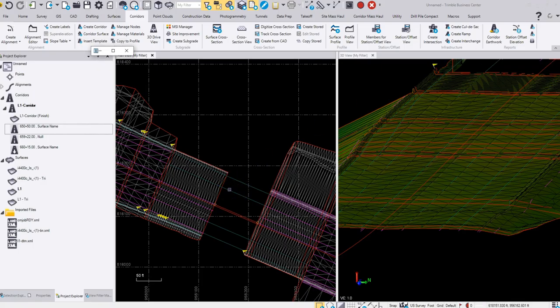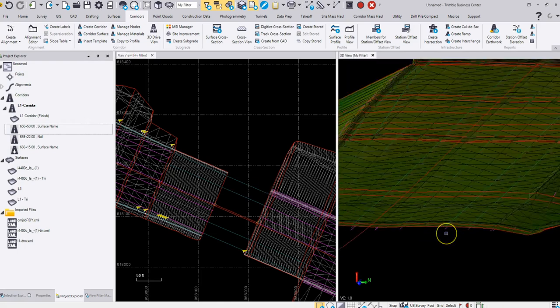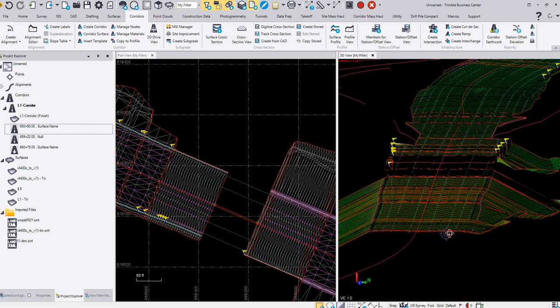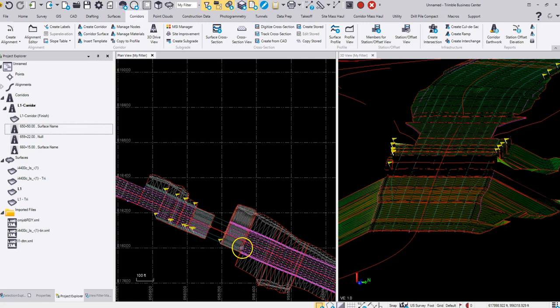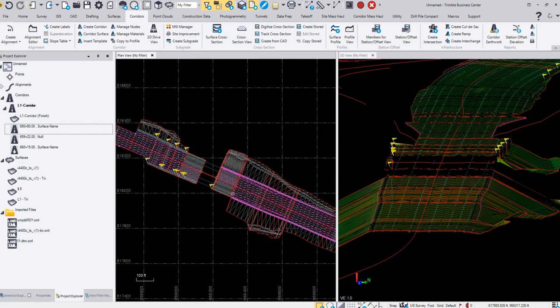Again, going back to, you can use these reference lines any way you want. So, if you brought in all the reference lines for the top based off of how you selected them, you could really get a little bit more detailed in the surface that you're doing. But I guess just for probably tighter numbers in a cross section, what I've shown here hopefully helps speed up the process of doing a takeoff on a corridor of this with this type of data.